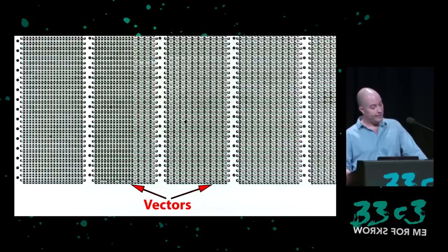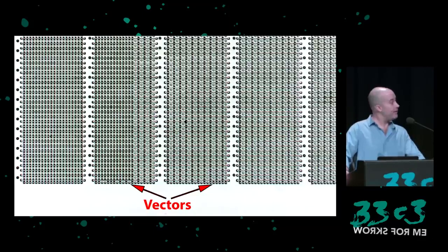This image shows the end of the ROM, where you can see a pattern covering most of the image due to a repeated pattern of filler bytes that occupy unused space at the end of the ROM. At the very end of ROM, the pattern is interrupted. This is where the vectors table exists at the top end of memory, indicating the reset address and the addresses of interrupt handlers. The ROM has unused space, the filler bytes at the end, and the vectors table at addresses FFF6 through FFFF.